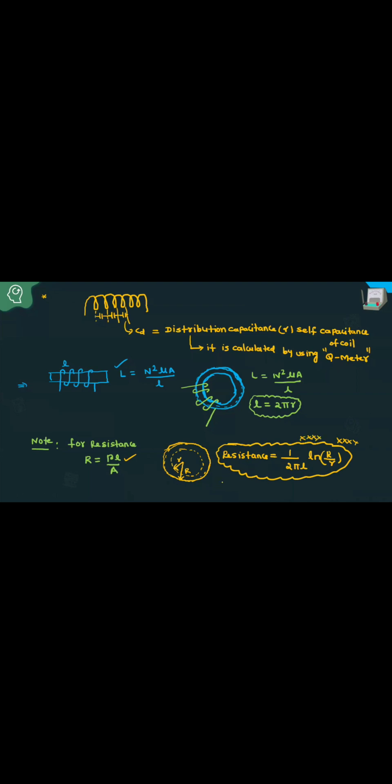Mainly in cables, you have to calculate the insulation resistance. Then you have to calculate this 1 by 2 pi L into ln of R by r.